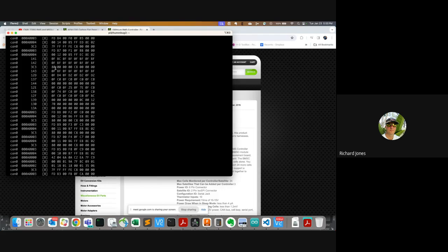And dilithium can do a similar thing. It can dump cell data over CAN bus, and you have a similar decode. But the address would be different, and maybe the ordering of the cell values would be different. That's where you just have to RTFM, and they describe what the contents of every byte of every message is. And then you get someone clever like Kevin to turn that into MQTT and actually show it on a screen for you, or however you want to display the data.